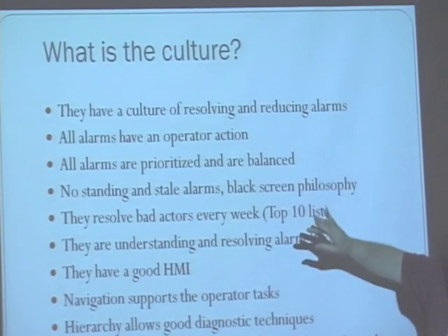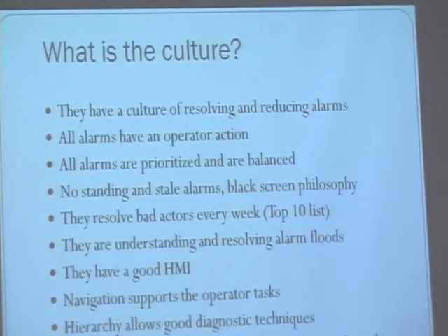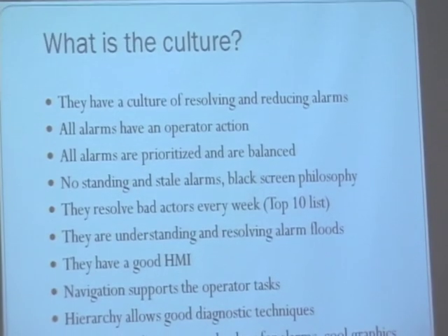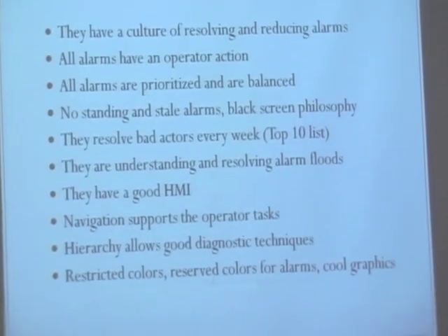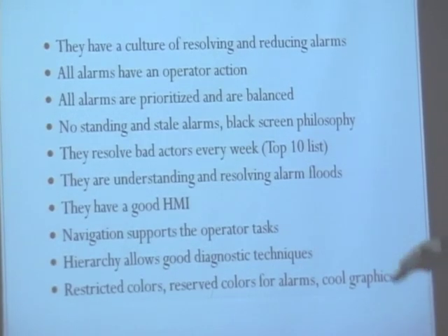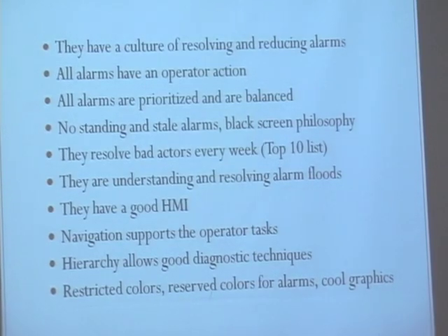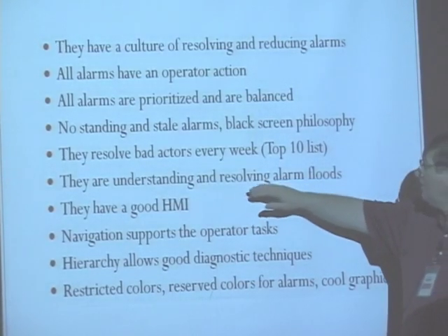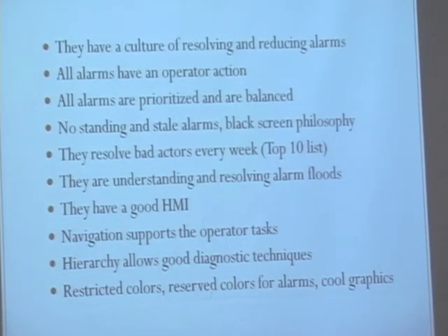They have no standing and stale alarms, and they have what we call a black screen philosophy. So if something's out for maintenance, that alarm is removed from the system. It's removed from the screen, maybe still recorded somewhere in a journal, but it's not up there in front of the operator. They resolve bad actors every week. They have a top 10 list that they work through on their alarm system. They have an understanding of resolving alarm floods. They're starting now to get more data and appreciation about what is within an alarm flood.